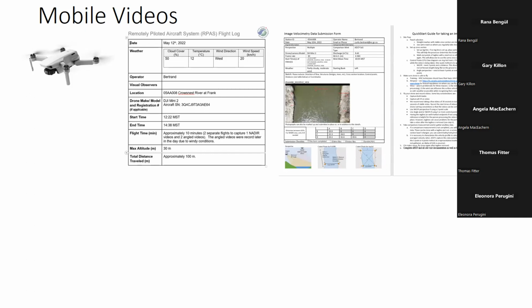It's easy to not capture a control point necessarily or mark where it is, because the tech isn't necessarily the one who's processing the measurement, at least at this time. And even simple things like, what bank did you start on for your cross section? Left bank or right bank? Those things sometimes get missed.